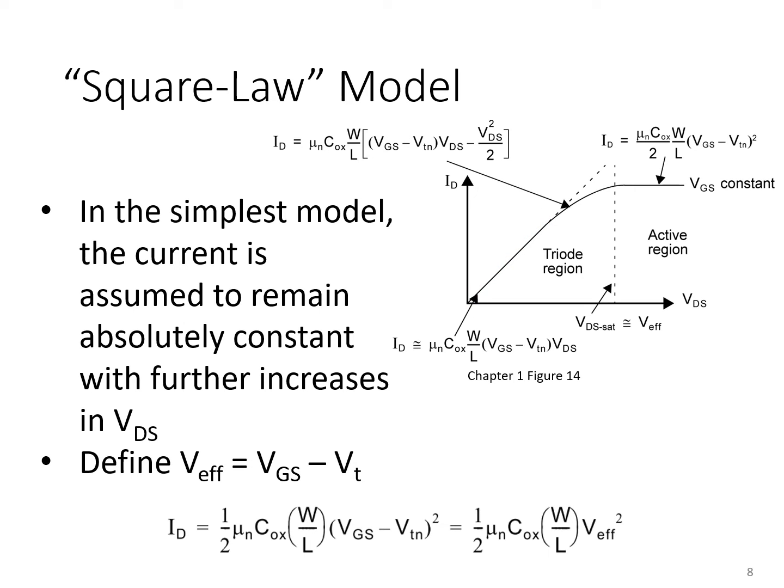You'll see that the current has a linear dependence on the gate overdrive voltage, our so-called V effective. That's again because larger V effectives increase the cross-sectional area of the inverted channel region, thereby reducing its resistivity and linearly increasing its drain current.